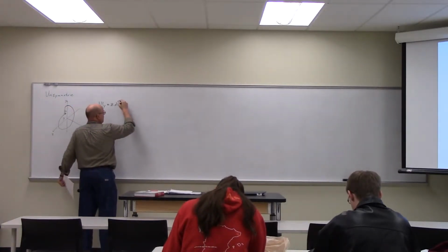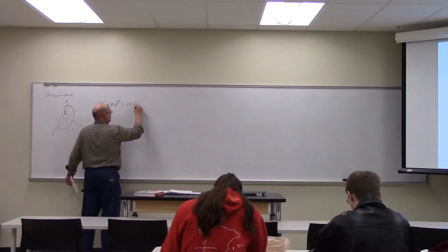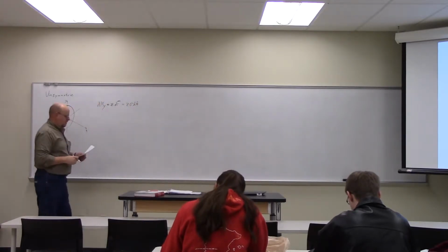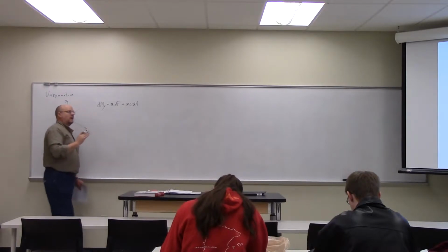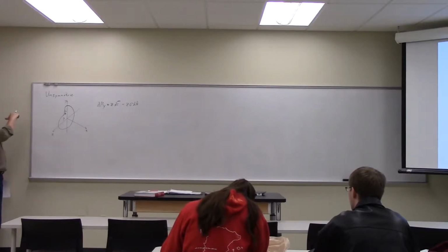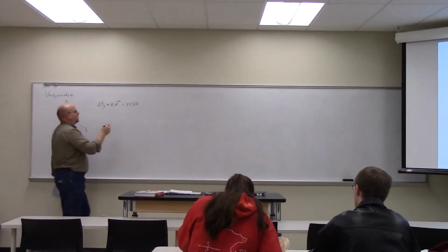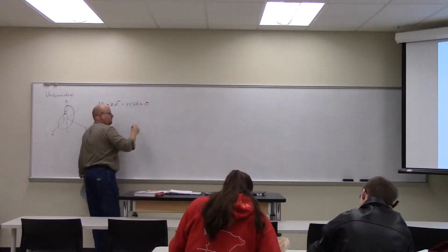Which we could write, based on the derivation we had for force last time, as z sigma dA. And if we're going to get it to bend purely, and by purely I mean only in the direction of the applied moment, so we apply a moment in the z and get a bend that is only in the z, then the moment about the y-axis must be 0.